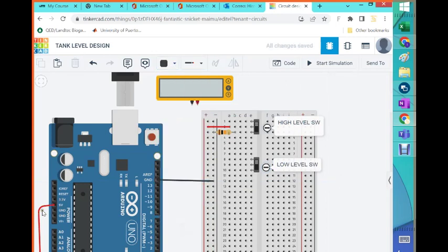Alright, so we have positive and negative into the rails. Positive rails and negative rail. See? So the resistor is right at the negative rail because it's a pull down. Now, where should I read the 5 volt from? Check this out. Gonna put it right here. And this negative will go to negative here.